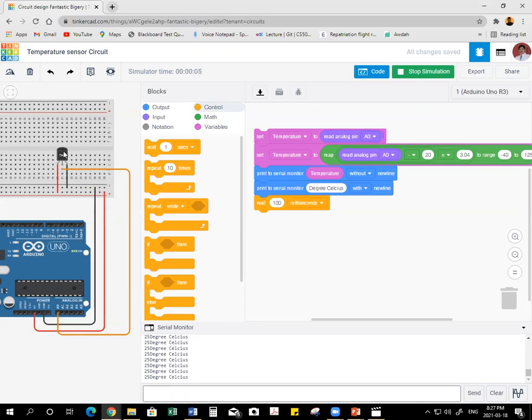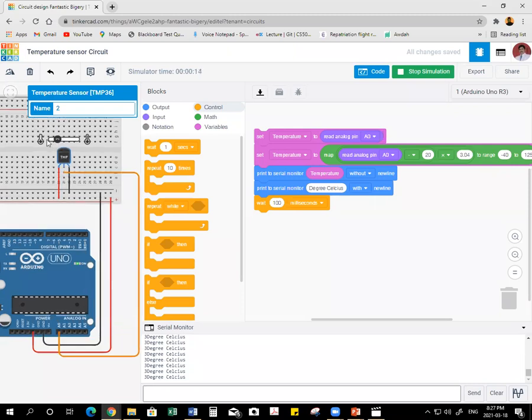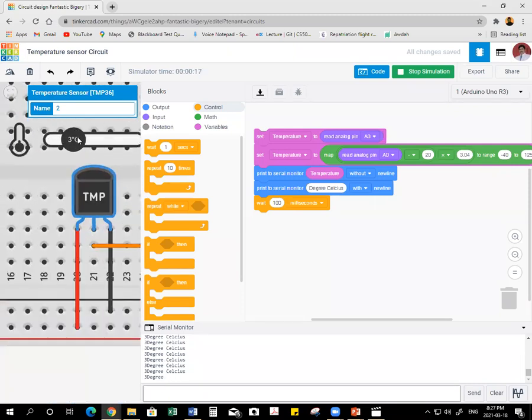Now, if we map it, if we go back, here also on the temperature, I will zoom this one. Here it is showing 3 degrees, -2, -6, so some -15. So it is -40. If we don't map this -40 to 125, it will not give the exact reading of what we are reading from the temperature. That is, the input A0 pin will read from 20 to 339 from the temperature. So we have to map that one.